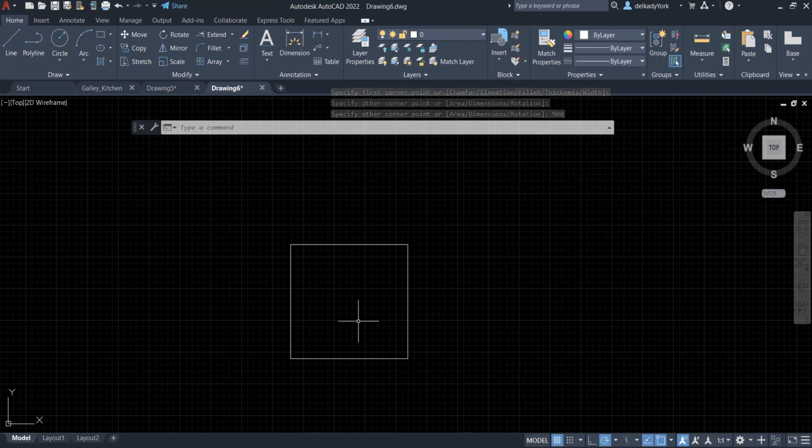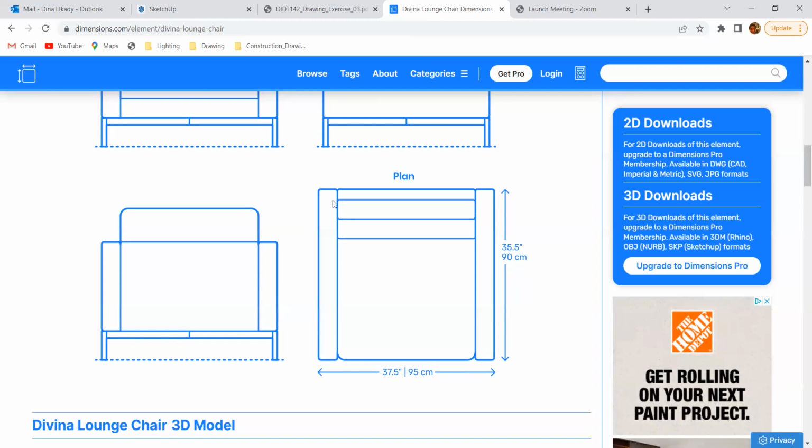The very first thing I'm going to do after creating this rectangle is offset it to the inside, because as you can see here, I have almost another rectangle to the inside. And then we're going to explode those, because as you can see, we have a lot of fillet edges on the side that we want to do. So that's the second thing we're going to do. But the first thing is I need to offset, or create, another smaller rectangle to the inside.